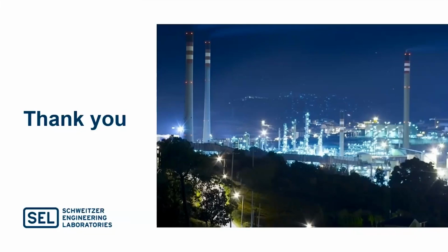We can utilize hardware-in-loop testing not just to test the algorithm, but also to mitigate risk and validate the design prior to getting out in the field, because trying to change or fix things in the field is going to be very troublesome. It will also allow us to test scenarios that we may never be able to test in the field, right? We may not be able to apply real faults or such behaviors. That can all be done in the lab, in-house, with the controller in loop, providing us with the highest fidelity. So in short, yes, we highly recommend it.